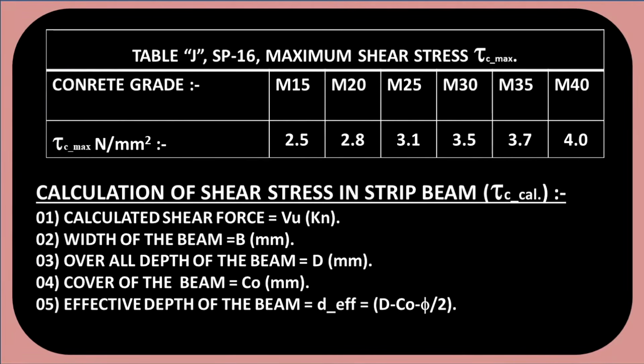Maximum shear stress tau C max. Tau C max required for the beam design. And the value of tau C max is given in this chart. It depends on the grade of concrete M20, M25, M30, M35 and M40.